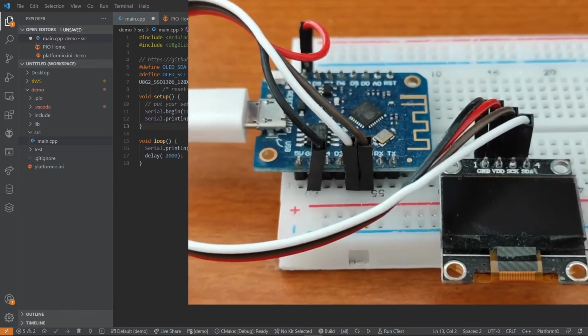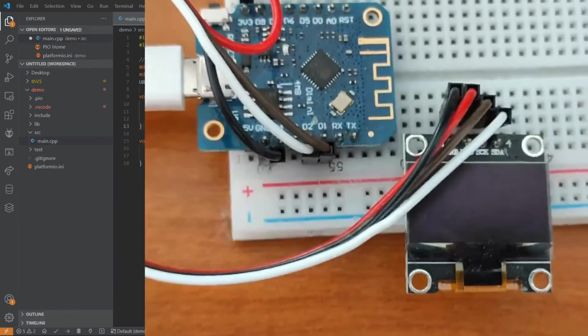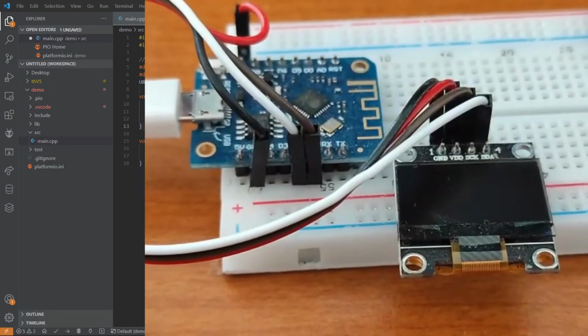Here, if you look at the screen, you see that you have serial clock and serial data, and you have to connect them to the D2 and D1 connections here, as you can see in the white and the black. So you have D3, D2 and D1, and you need to connect, of course, the ground to the ground. And the voltage, I use 3.3 volts over there. As you can see, I use 3.3 volts. Okay, this is how we initialize it.